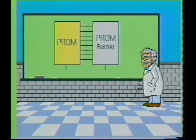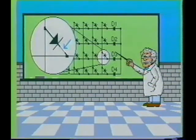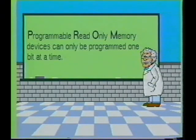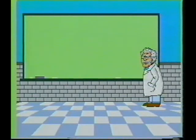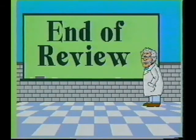To program the PROM, a special piece of equipment is used. It is called a PROM burner. The factory fresh PROM consists of a matrix of fusible links. An intact link produces a binary 1, whereas an open link produces a binary 0. PROMs are programmed one bit at a time. This concludes review number 2. Next, we will examine the EEPROM.